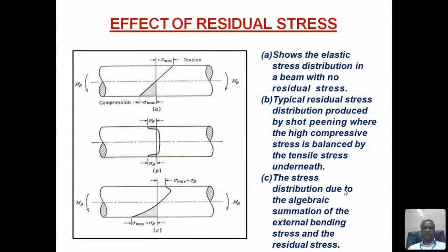Corrosion, again, corrosion definitely will affect the fatigue life. Now if you see this graph, crack growth rate versus delta K, if there is an inert atmosphere, the crack growth rate is slower, but in the corrosive environment, the crack growth rate is faster. Okay, the dotted line shows the corrosive environment. This is the inert environment. Inert means a vacuum. So there are two different environments. In the corrosive environment, the crack growth rate is faster. Why is it faster? You see the slope of the curve is higher. M is more in the corrosive environment.